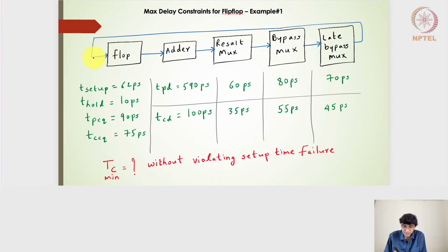And it should reach the second clock edge just before the T setup time, so that it gives the output after the TPCQ of the second clock edge. Similarly, it will keep on pumping the output back to the input of the flop designs, and then once again the computational output will be provided at the third clock edge, the fourth clock edge, and so on.